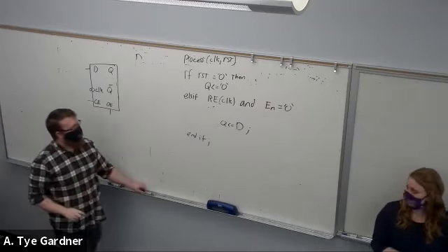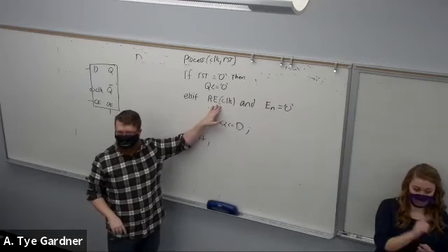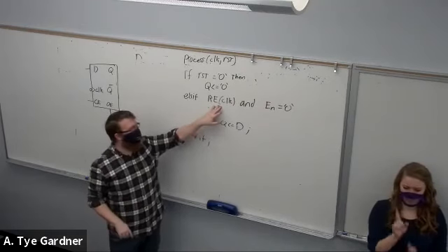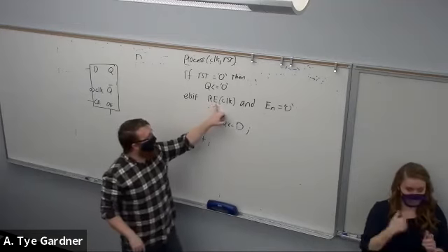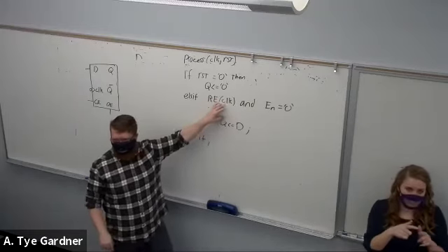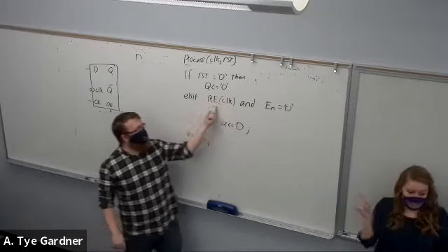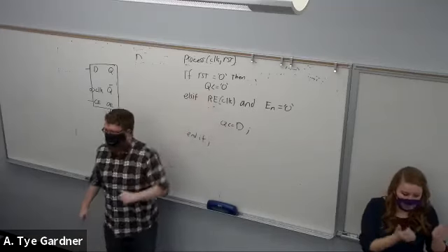I recommend against doing this for the rising edge condition because the errors get weird on this one. If you've done a gated clock or something and it starts throwing errors, if the enable is on the same line versus being embedded, it gets harder to hunt down. I don't mind using multiple conditions in other situations. I just recommend against it in rising edge.